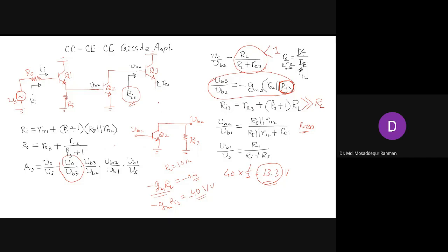Whatever gain you get, that resistance will absorb. The load will not get that benefit, right? The voltage at the load will not change. It will not improve, right? Because the resistance will consume. So unnecessarily we will be increasing the loss in the circuit.